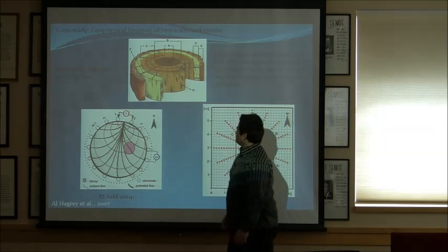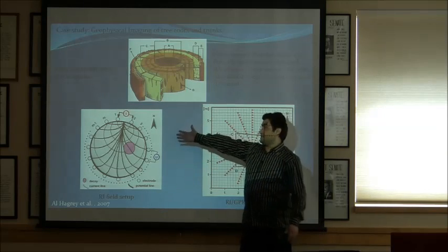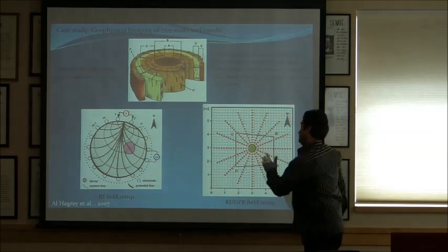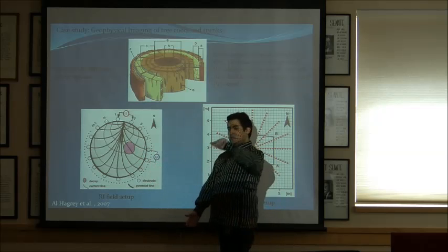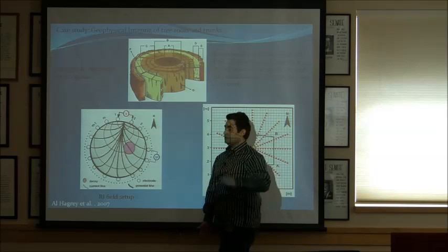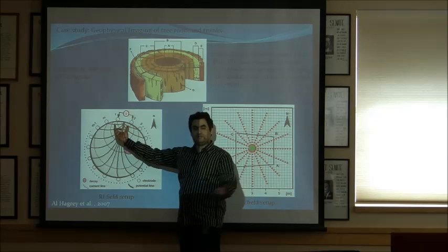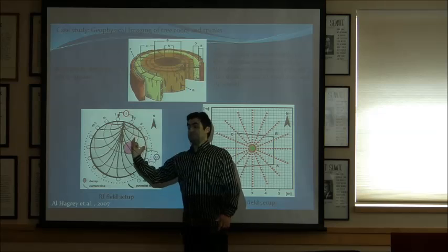Okay, so for tree trunks, people use two methods: resistivity method and seismic methods. Here I chose to present resistivity. It's simple: you pick any tree, put electrodes around the trunk, and it's the same principle as surface-based resistivity. You inject the current, and you measure the potential difference.